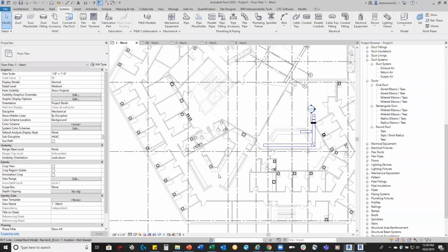But sometimes when they're modeling, they forget about that, and you'll find this is an easy way to catch a shaft that shrank from the wrong side, or if they completely forgot to put a shaft on a floor. Just drawing a couple reference planes in there and reviewing those all the way up will show you your routing options, if you will, as you move forward. Same thing with stacked mechanical rooms, electrical rooms, whatever you can think of. Taking advantage of reference planes is a huge benefit there.